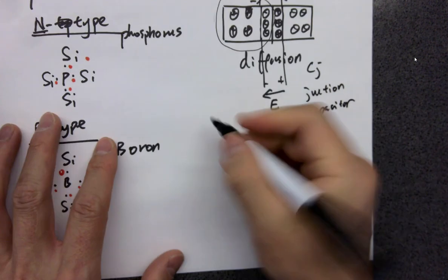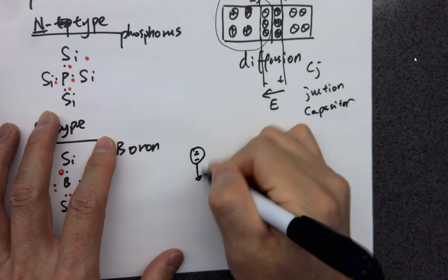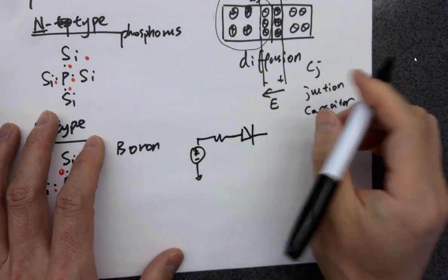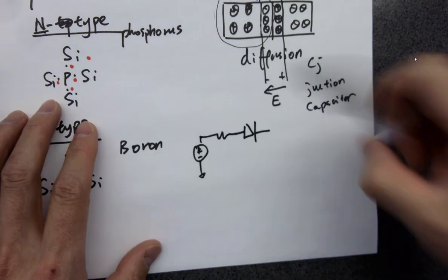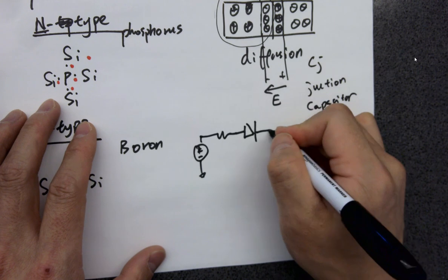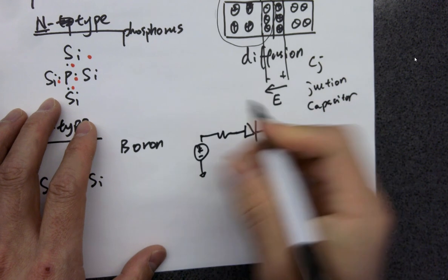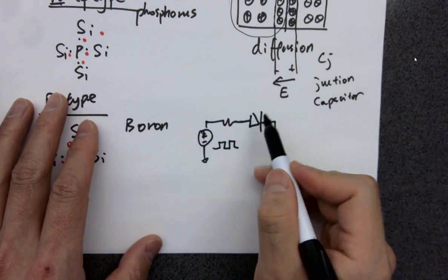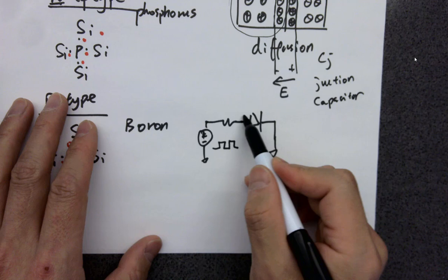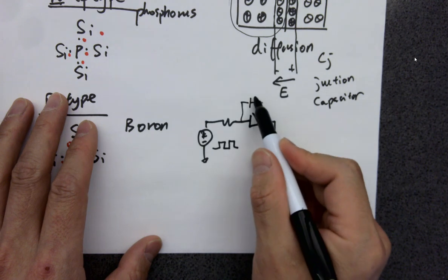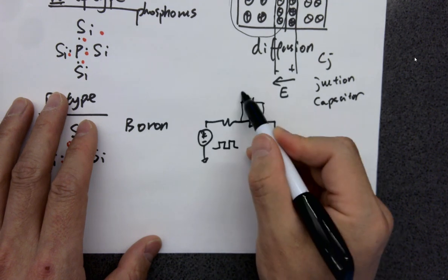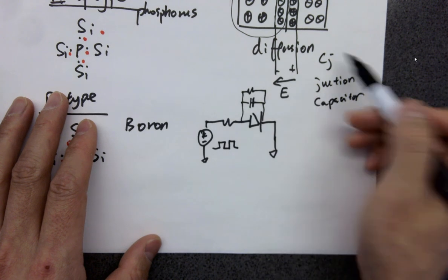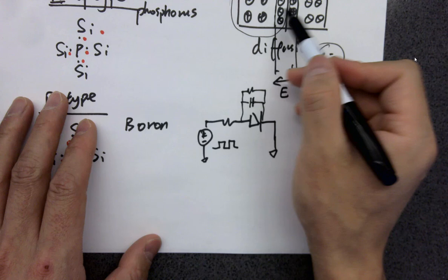So you know that when you are charging and discharging an LED, it's not just a resistor model. If you model it, it should be a cap and a resistor for this diode, right? Because it has a junction capacitance built in the PN junction.